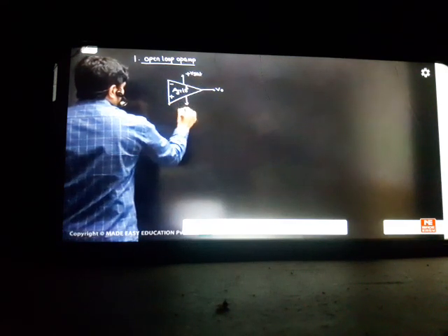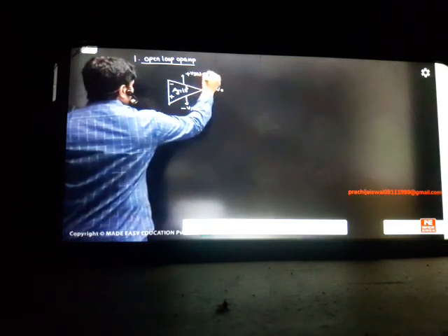In place of writing batteries, you write saturation limits. Minus V set, this answer is supposed to be 10 volts given. This answer is minus 10 volts given in the problem. 10 and minus 10 symmetrical values generally we have to give in the op-amps. And the next, I kept here one resistor R at this point, one practical resistor in series to the op-amp.